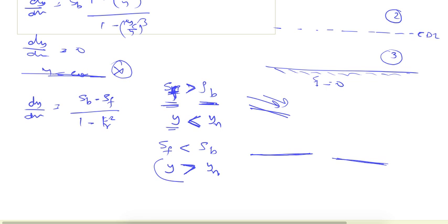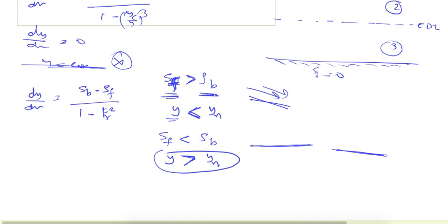So we can use these two criteria to study these equations. It is simple. If the friction slope is greater than the bed slope, then the depth of flow will be less than the normal depth because flow will accelerate. And if the flow is accelerating, it means the velocity is increasing. Velocity increase means a decrease in depth, and the opposite is the case with this one.